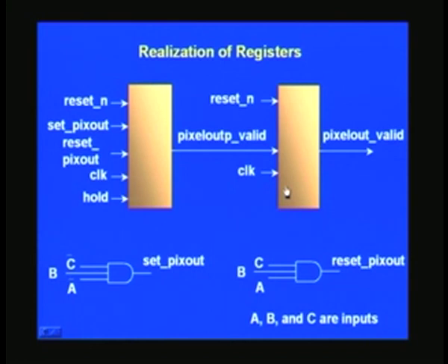And we have one more flip flop here that also has similar signals, for example reset and positive edge of clock, and just as we have this pixel out P, we have a pixel out here. Actually this is the signal that we want, and this is actually a signal pertaining to a previous clock. So, for example, in a train of clocks at a particular clock, this has become mature and it has written into this, but that is not the point of time that we want to extract this information, because data which is coming through another path is normally delayed because it has to go through several complex processes such as addition, multiplication, etc.